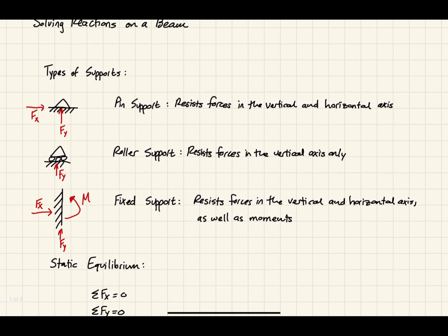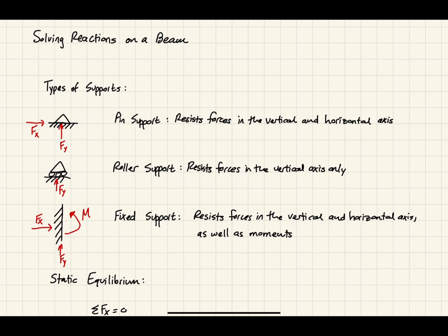So I want to kind of expand on rollers and why they don't support the Y direction. How I like to think about it is, let's say, I guess I'll draw it up here. If I'm standing over here, and let's say I have a large piece of plywood or something, just like that. I have wheels, and imagine there's some wheels over here too. We can't see them. Let's say I'm here and I want to push this over. Well, if you can imagine, our plywood would just roll right off, and our rollers wouldn't really help us in that case.